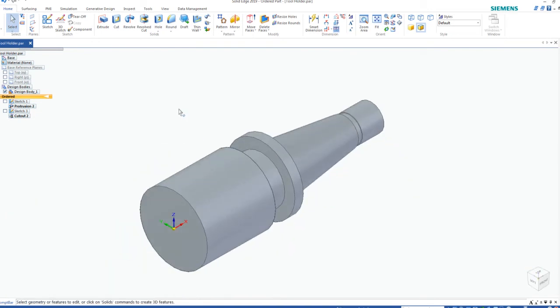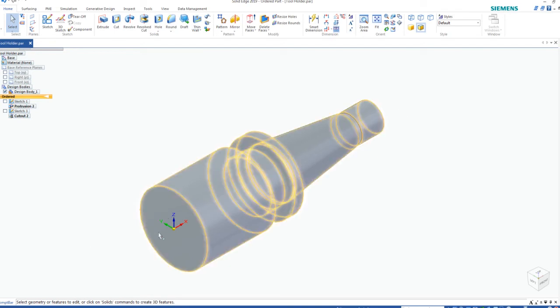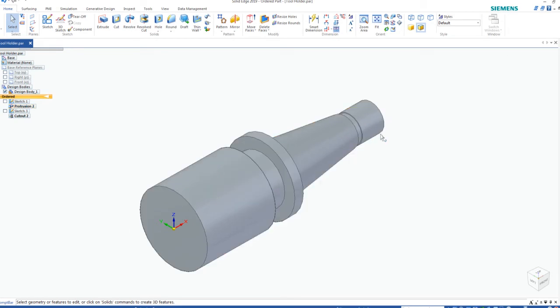Okay, there are a couple of main features that we have to add now, and that is there's a bore hole that goes all the way through the piece on both ends. On this end, it's just a straight bore hole. On the other end, it's a counterbore hole, which also has a threading feature on it. So we're going to start by creating this bore hole here, and this bore hole here gives us a limit, and then that limit is 1.5015 to